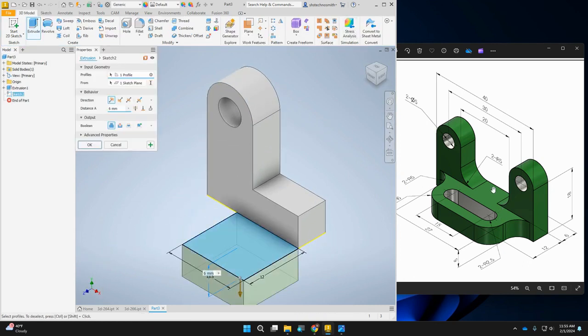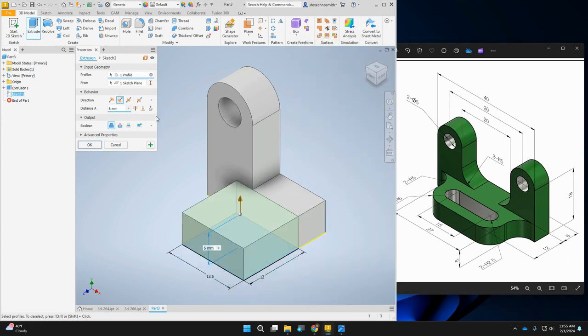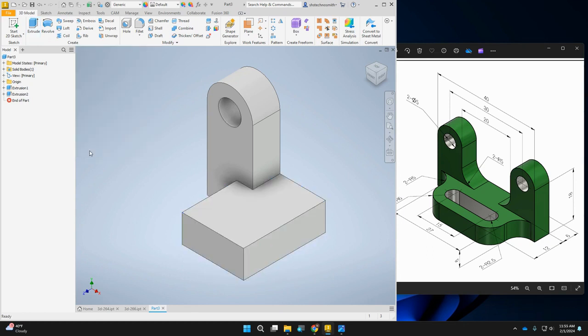Extrude that. All right, comes right into the surface. We might have remembered from before that it was 6, and that's already there. But I'll show you another way to do it. We can go to face, and then it will bring us there. So if I had done something else and I didn't have that 6 in there, maybe I closed this, came back to it, I can extrude, and then go to face and then click on that face. And then that kind of joins them together.